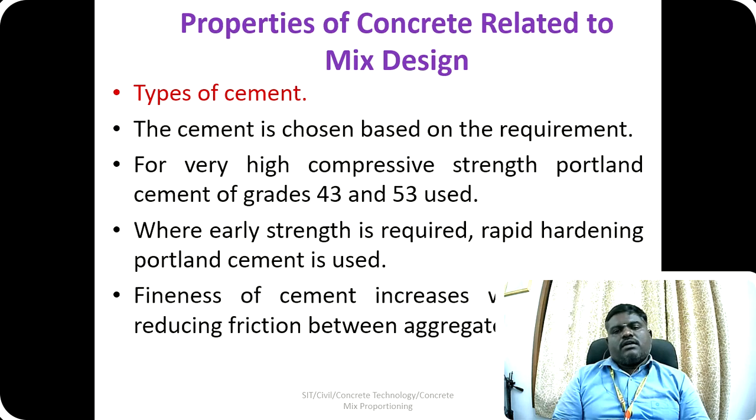If the cement grade is 53, then after 28 days the mortar cube strength should be around 53 Newton per mm square or higher than 53 Newton per mm square. So these are the two grades of cement we are using in the field.